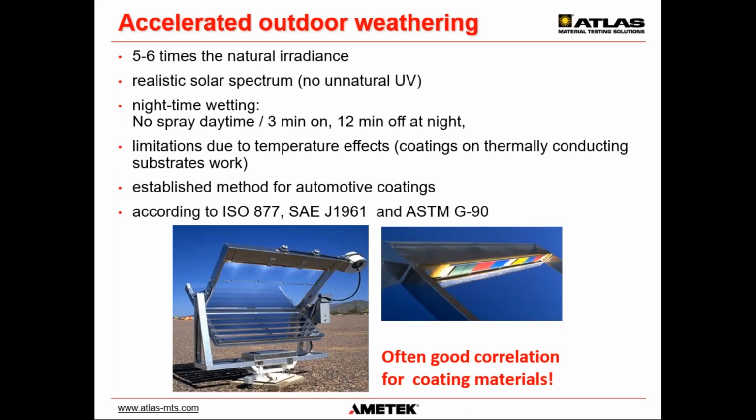I mentioned the solar concentrating exposures, and these types of exposures are specified in ISO 877-3, SAE J1961, or ASTM G90. The nice thing about these standards is that you can achieve pretty high levels of acceleration utilizing natural irradiance.